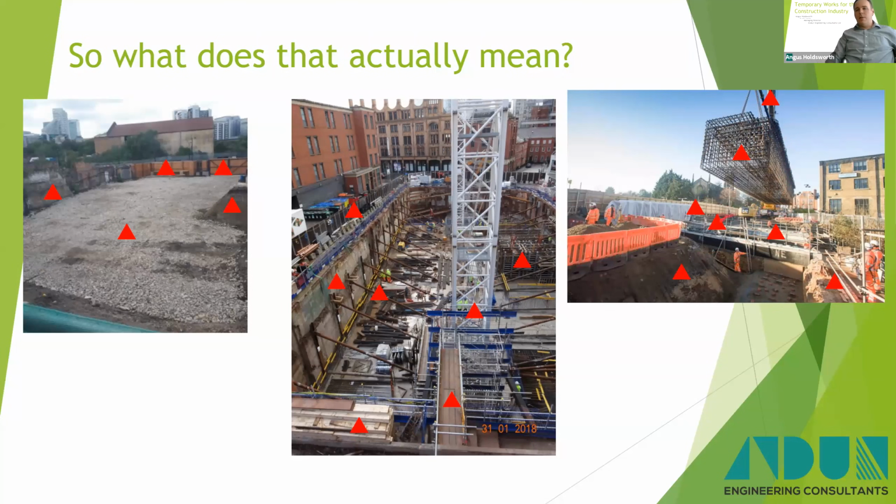You've got temporary stability of the bridge itself when the bridge deck was demolished. You've got temporary earthworks stability here. You've got a temporary access deck that you can't really see in there. You've got assessment of the existing structure in temporary conditions here, where you've got the wing wall with concrete pressures when you form this part of the abutment here. So there's lots of things that become temporary works. Obviously, the level of complexity determines how much attention you need to pay to them.